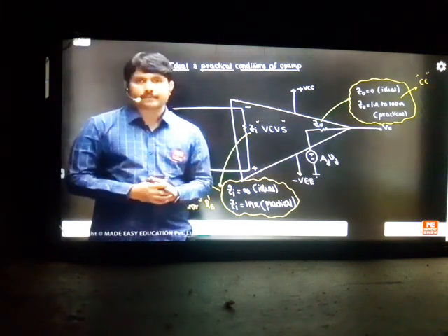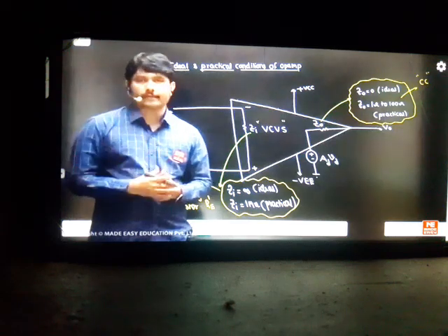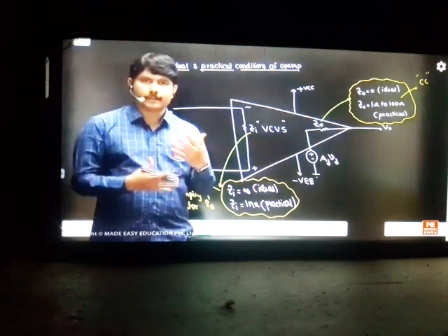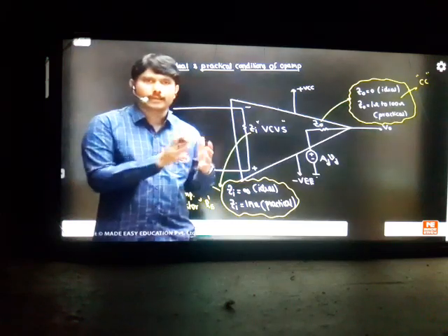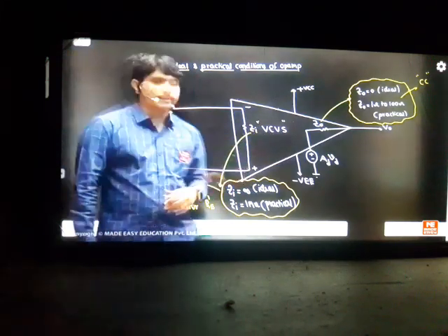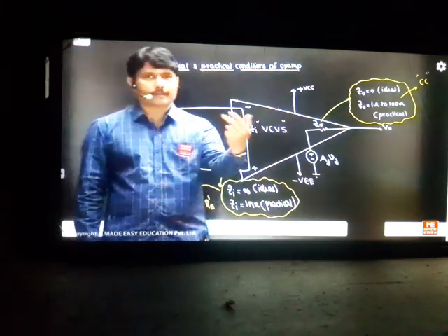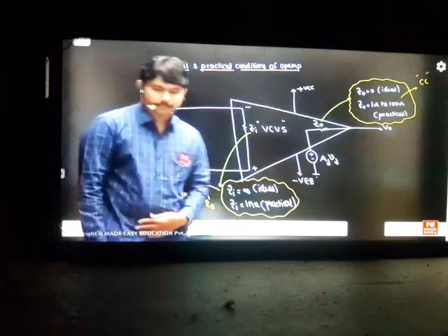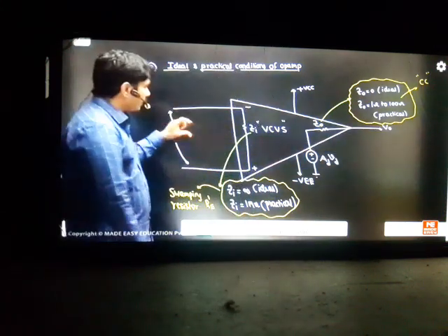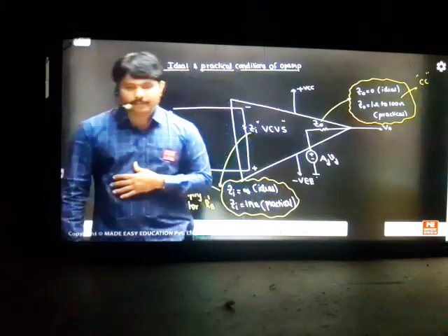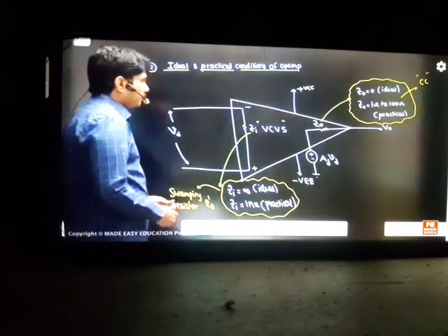But when you go to power electronics, they are not unilateral, they are bilateral. Triac, diac, electrical students will learn. They do not have unidirectional behavior, they have bidirectional behavior. That's why they work like switches, not like amplifiers. Because the main rule for an amplifier is that it should be a unilateral device. That's why this arrow represents it, not a triangle. It is telling that the current will flow from input to output. The current will not come from output to input. Only one flow of action. You cannot get opposite control. If you sit here and control something, nothing will happen to the input. If you control at the input, something will happen at the output. That is called the unidirectional technique. So this completes 2 answers.